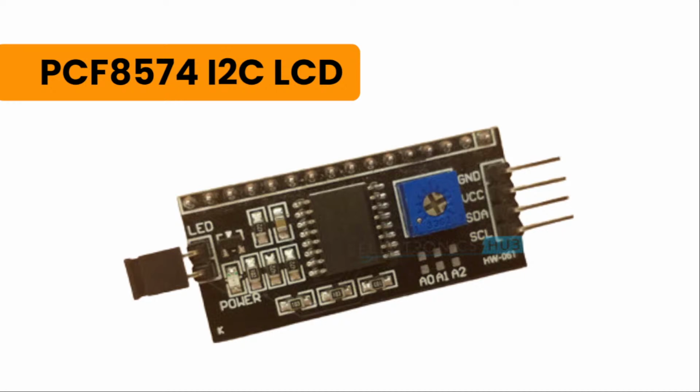So using that many pins of a microcontroller just for a simple character LCD display is not desirable, right? Especially if you are designing a project with a lot of sensors and devices connected to the microcontroller, it takes a lot of GPIO pins. It will be clumsy, right? So to overcome this drawback, we are going to use this module.